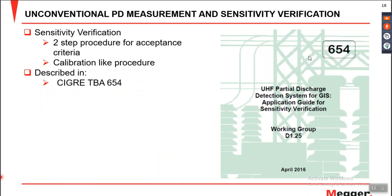Now coming to the question: when we perform the conventional measurement, we can quantify the charge in terms of picocoulomb. But a UHF measurement is just like sensing the partial discharge signals by means of a sensor. So you cannot quantify the charge in terms of picocoulomb; what you measure is a ratio in dB microvolt or dBm. So how can I conclude whether the amount of partial discharge measured with the UHF sensors is greater than or equal to 5 pC, or less than or equal to 5 pC?